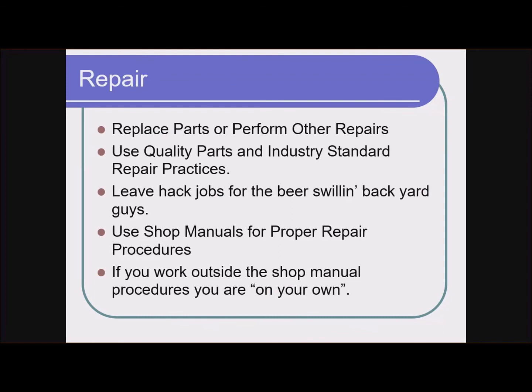Now I'm walking away from the job saying I don't know what to do. It has to be the thermostat. The engine's not getting hot. It's not like somebody installed an extra good cooling system, right? Everything else is the same on the car. It's all factory stuff, and the engine's not reaching operating temperature. There's only one possibility. It's the thermostat, right?